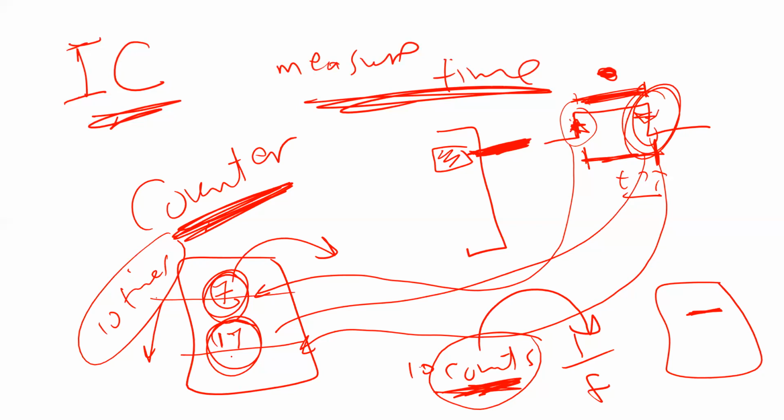Why is it very easy? It's just two interrupts, man. One interrupt, you're going to get a number. In the other interrupt, you're going to get another number, and then you can do the calculation. And the microprocessor is free all the time. All I need is a very little time for my microprocessor just to take two numbers. Other than that, the microcontroller is free and can do anything else. It's not going to check if this pin is 1 or 0, whatever.